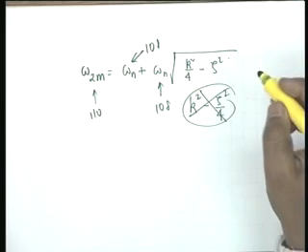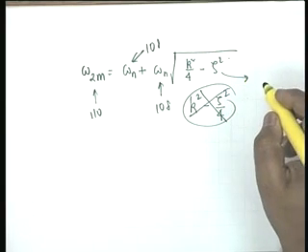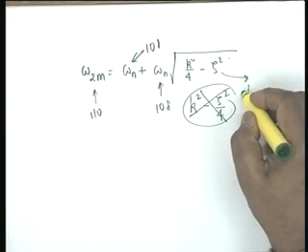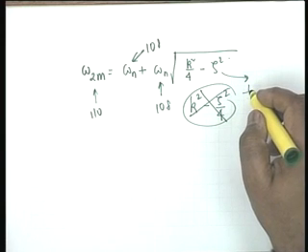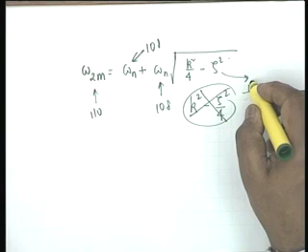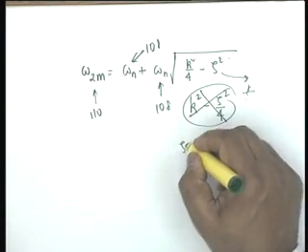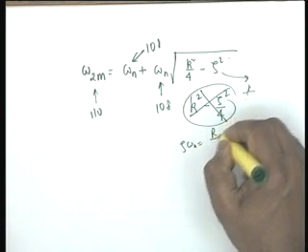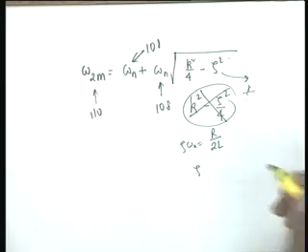All that we are given now is this is 110, this is 108, k is not known, but zeta, how do you find zeta? Zeta is r by 2, zeta omega n equal to r by 2L, from which you find out zeta.